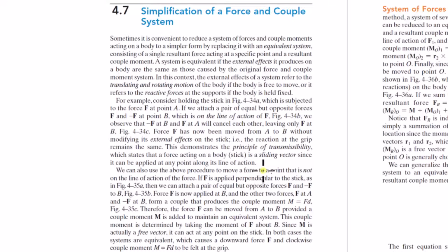So all forces on rigid bodies, and this is not just in statics, but even when we get to dynamics with moving and accelerating bodies, all forces are sliding vectors. What this is saying is that you can slide a force along its line of action, and no matter where you place it along its line of action, the external effects it produces on the body are the same.